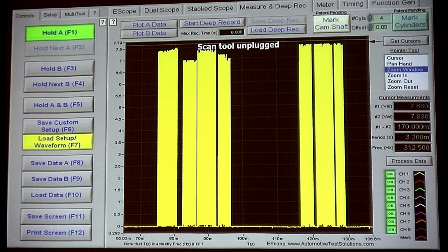You're telling it to target a voltage on an edge, and whether it's going up or falling, and I start a clock. An internal clock is going to run, and these clocks are really important. We're going to talk about this in depth. These clocks are what set up the divisions or the bit timing. Without these, we have no communication.